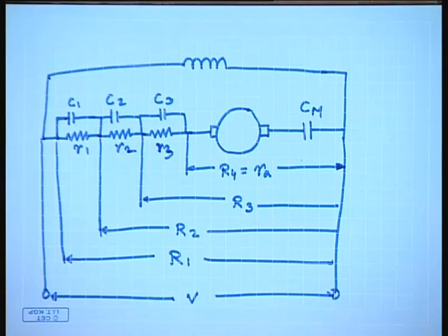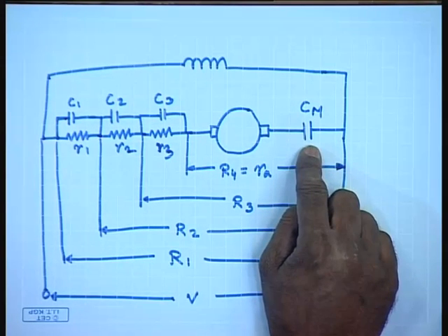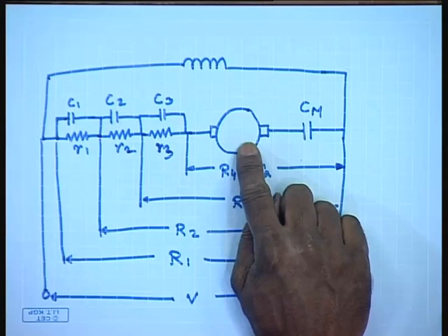Now, in addition to this simple scheme, of course, many protection features like no volt release, overload protection, etc., are also provided with a commercial relay contactor based starter. So, when you push a start button, first the main contactor closes and the machine starts accelerating.